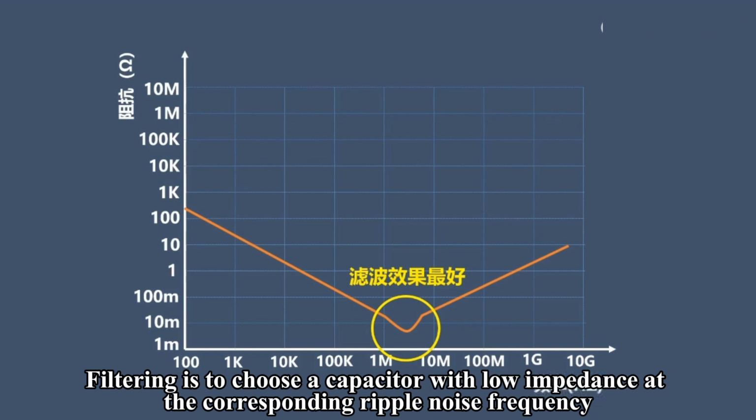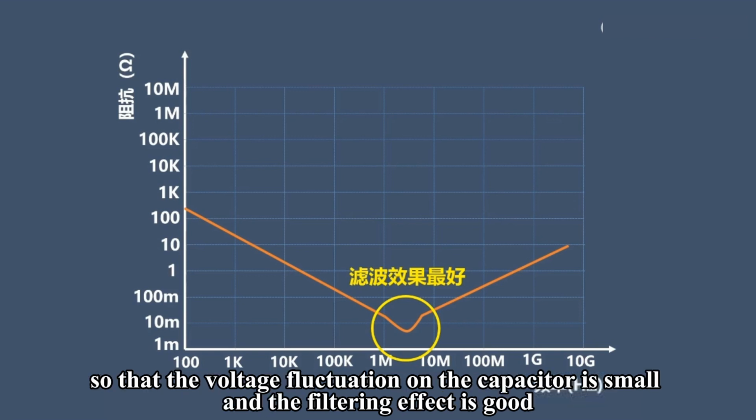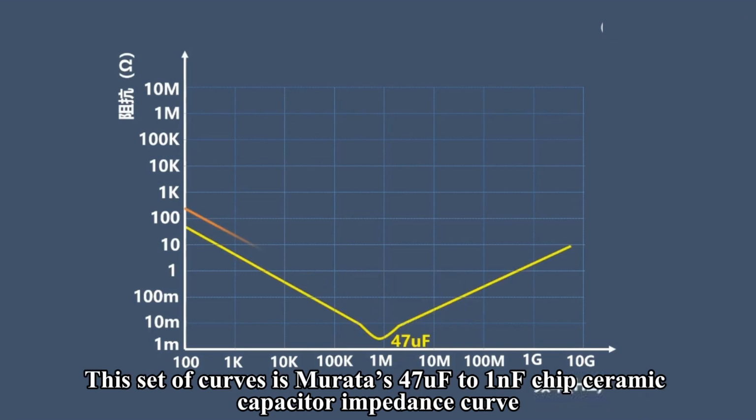Filtering is to choose a capacitor with low impedance at the corresponding ripple noise frequency so that the voltage fluctuation on the capacitor is small and the filtering effect is good. This set of curves is Murata's 47uF to 1nF chip ceramic capacitor impedance curve.